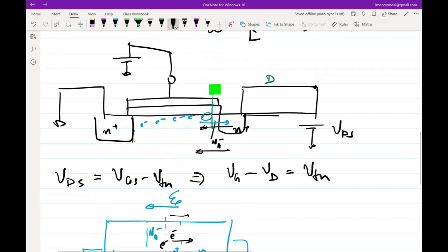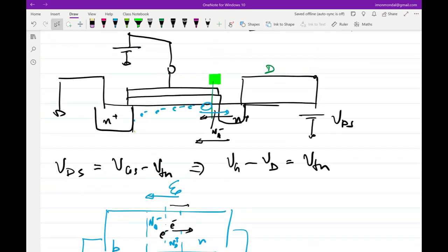So the flow through the pinch off region is similar to this, just that the carriers there are not getting generated by thermal generation. They are getting pushed into that region by the whole bunch of electrons that are there in the remaining part of the channel. So those remaining electrons are making their way to the depletion region, which we are marking as a pinch off, and the existing electric field is pulling them away towards the drain, right? So there is a current flow. I hope you agree that there is a current flow, right? But the path through which the electrons go must have some steady state density of electrons.